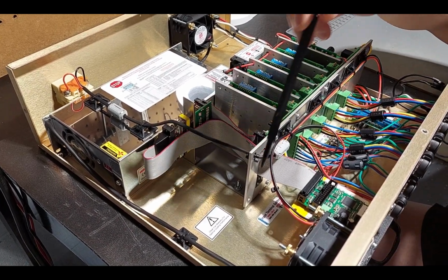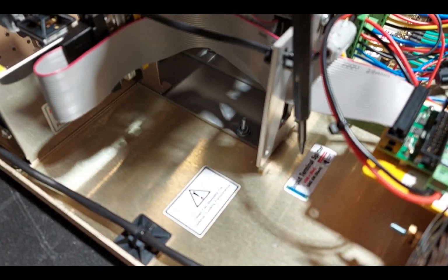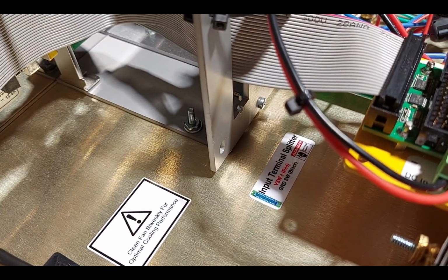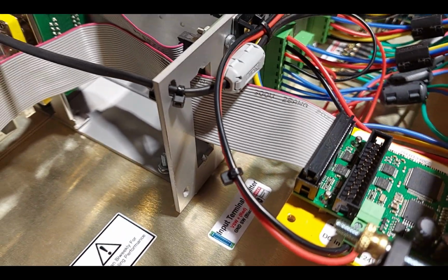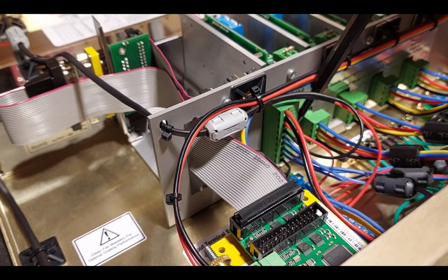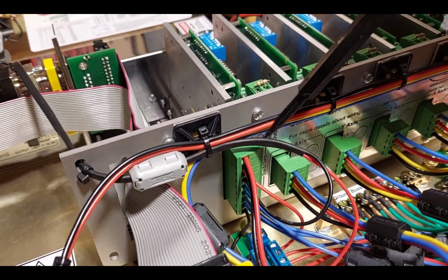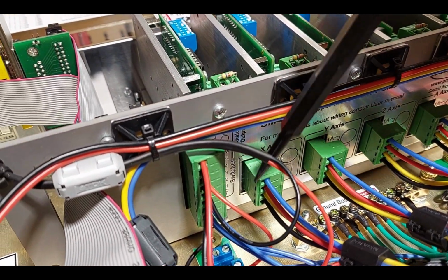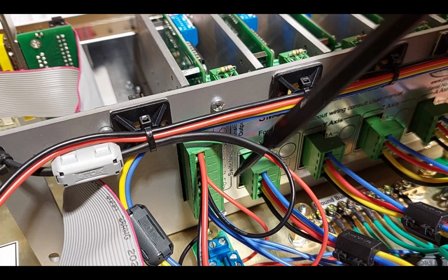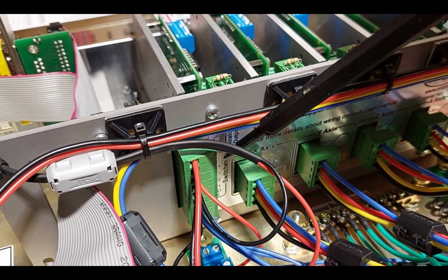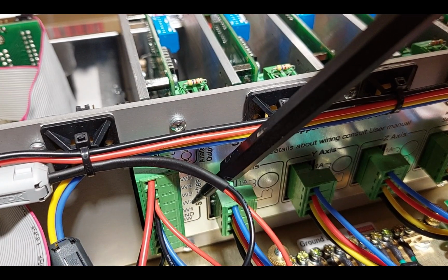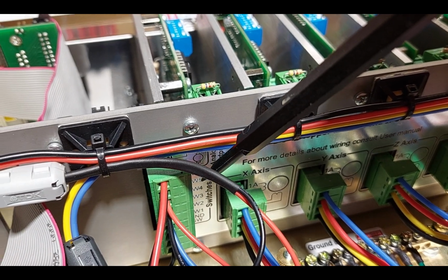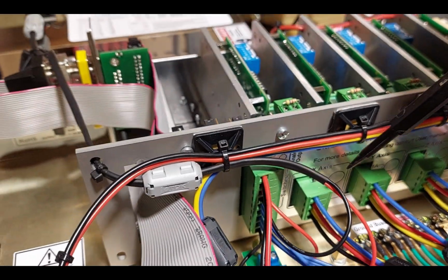Now, coming over here, you can see our input terminal splitter. And this is for a VSW signal for all of our inputs. So once again, input terminal splitter for our switches. And you can see the VSW red lead. And then we also have the black lead on the bottom, which is the ground for the switches. And you could just read the drive right here, and it tells you exactly what's connected. Switch 1, switch 2, switch 3, switch 4. Switch 5 is allocated to the E-stop.